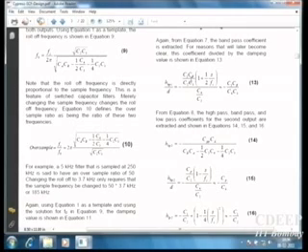So, some definition like oversampling is Fs upon F0. And some examples, for example, suppose you have a 5 kilohertz filter and your sampling frequency is 250 kilohertz, therefore your oversampling ratio is 50. This is the definition they have here for oversampling.